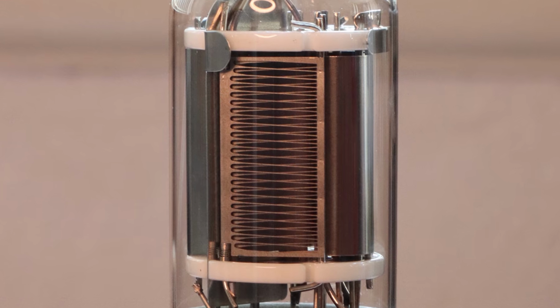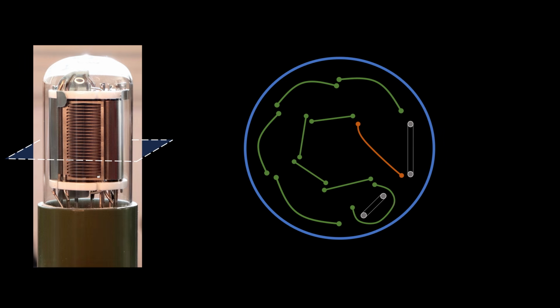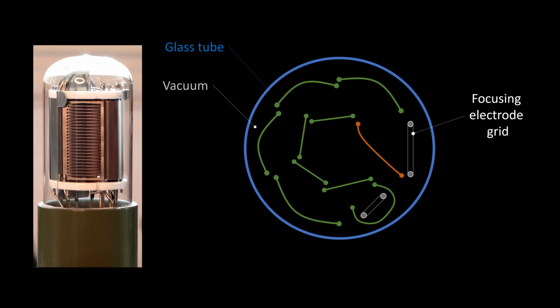And I guess the best way now to explain how the device works is by means of a schematic cross-section showing you the internal layout in more detail. Here is a glass envelope with the high vacuum inside. This is the wire mesh through which light can enter the device, also called the focusing grid. Behind it is a photocathode, which is coated with a thin layer, usually consisting of a mixture of several low work function metals, like the cesium that was discussed in the photoelectric effect.